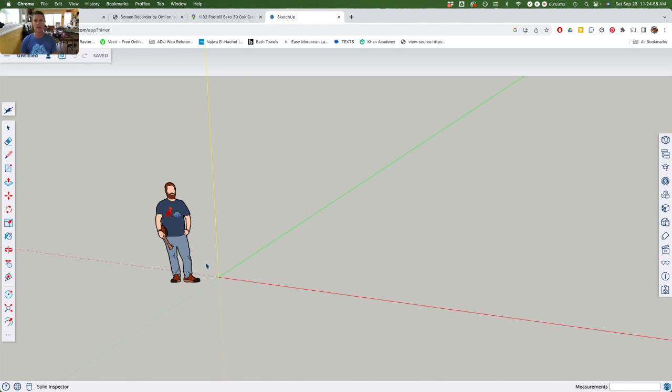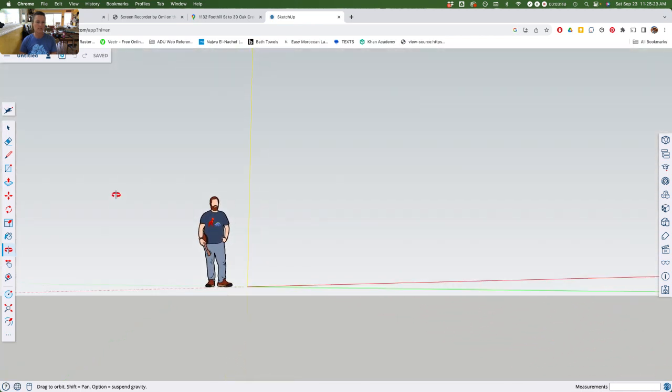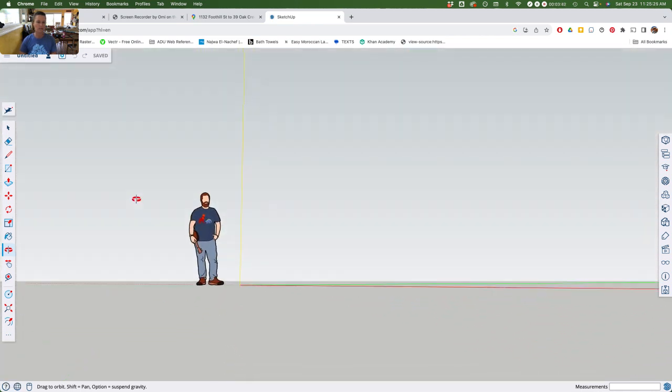The first is how to navigate in your model. So these tools, just like if you hover over here, it'll give you a hint of what something is. If you hover over a tool, it will tell you what the tool is, and then it will tell you the modifier key. So you use the modifier keys a lot. The first tool that is important is the orbit tool, which the modifier key is O. So if I click O, I can orbit. So this is how I drive around in the model.